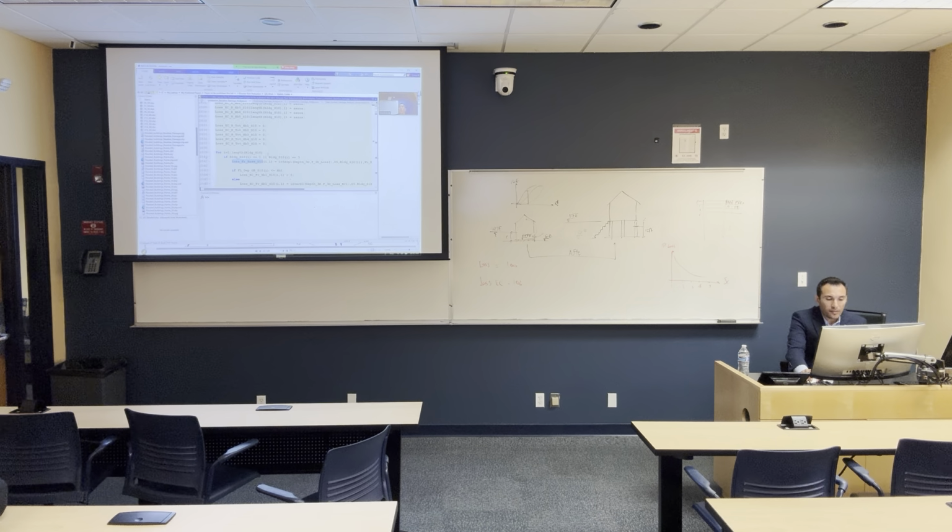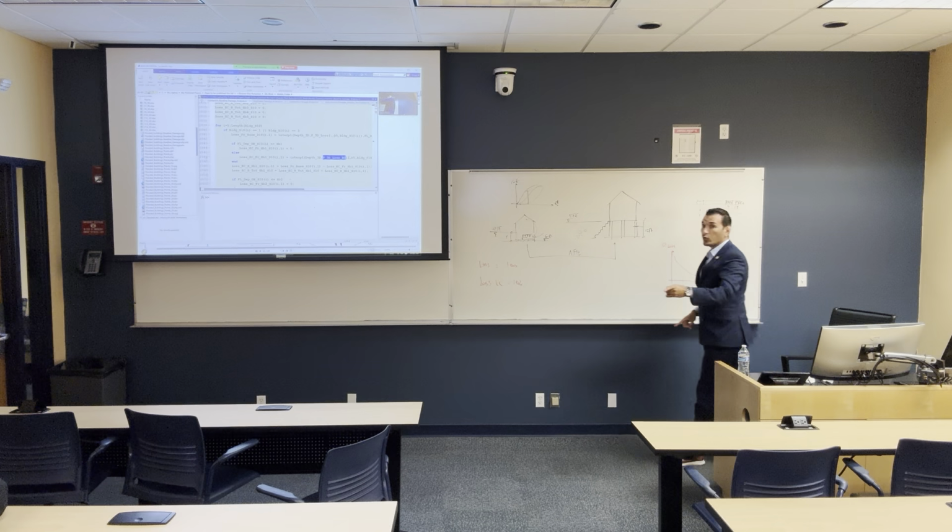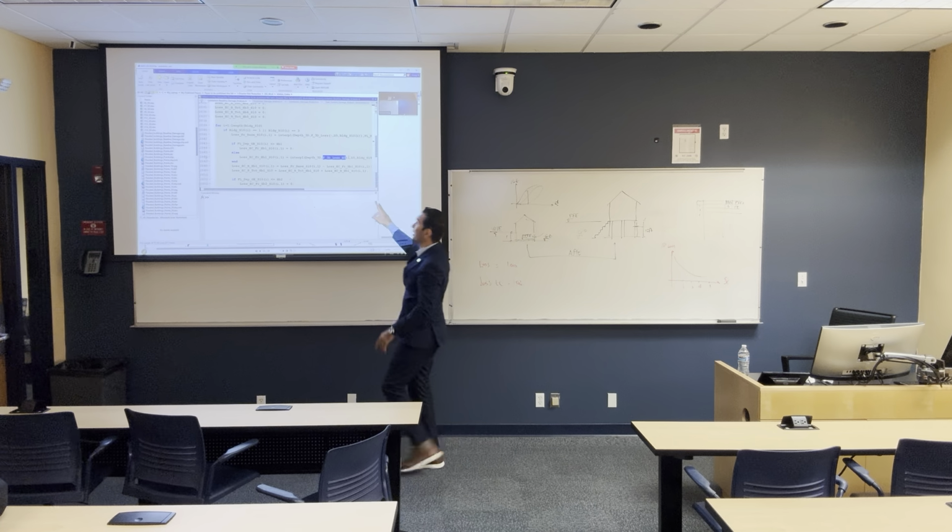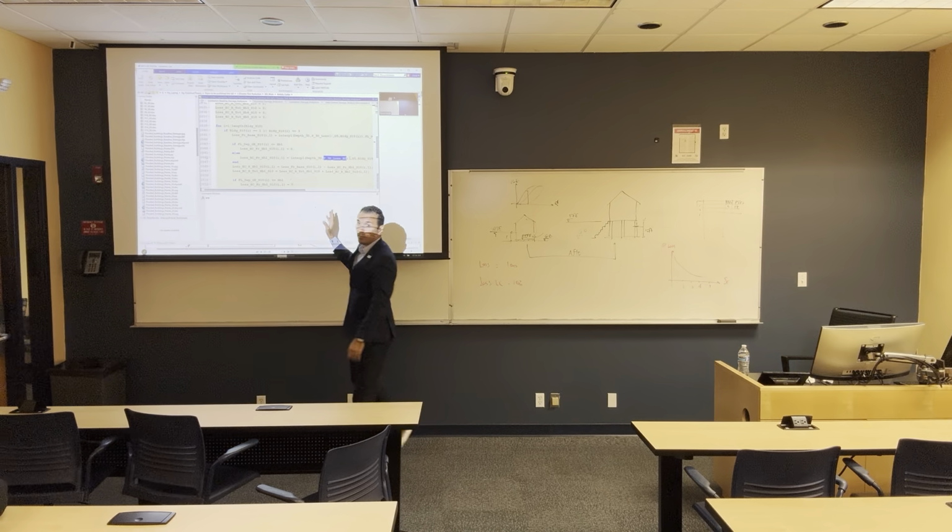Alright, so I do the same process, look here. Once I calculated the base, I calculated the flood loss. If the flood barrier is higher than the flood depth measured from the ground elevation, put the losses with elevated component 0. But if not, go interpolate in the function loss elevated components, and look at this function that I'm interpolating from: F3D loss elevated components. The one that we did last week was the same thing, but we said F3D loss and we stopped.